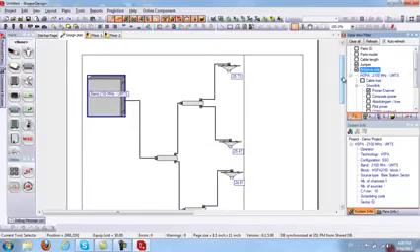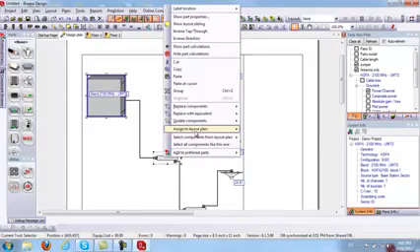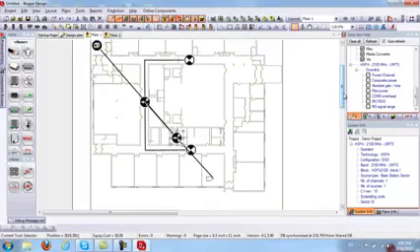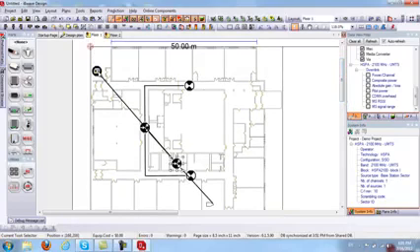So notice I have added a base station sector and a splitter. I did not assign them to any floor. So from here, I want to go ahead and assign them to floor 1, assuming that our equipment room is located on floor 1. So we'll do floor 1. Automatically, they appear here on my layout plan. So I'm going to assume again that my equipment room is located here.